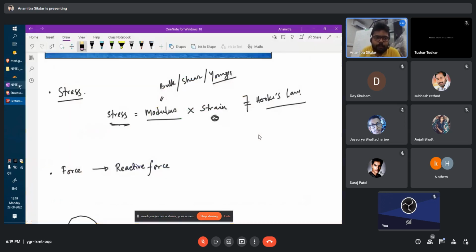Say for example, you have a circle here, right? And you are deforming it, right? So eventually you will get a shape of something like that, right? So this part will be extended and this part will be compressed, right? So in that circle, if this part gets compressed and this part gets extended, there will be one point in between somewhere here which gets neither compressed nor extended.